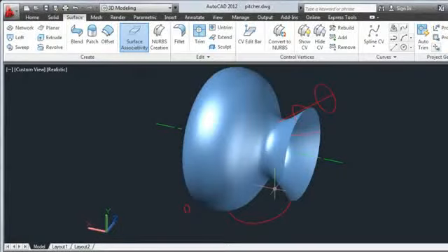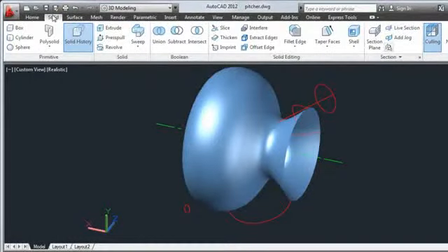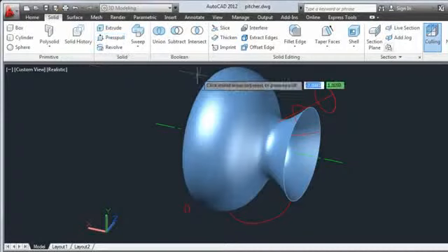So far, so good. Now I'll extrude this circle into the body of the picture. This solid will be used to trim the surface and form the cutout for the pour spout. From the Solid tab, I'll select Press Pull. Notice the circle highlight as I hover.